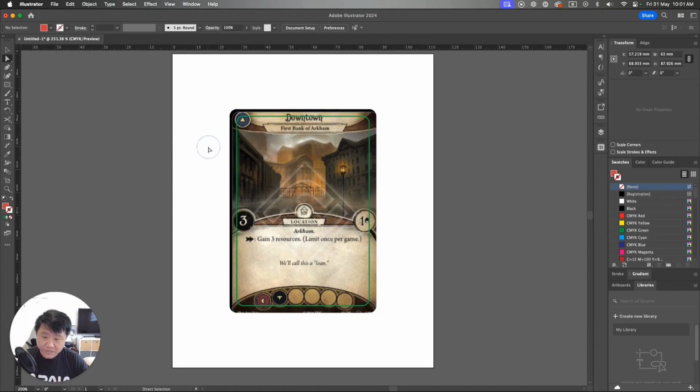So this is a 1 mil drift. Note that every manufacturer has different tolerances. Some have 2 mil drifts. If you're using a local print shop, their drift tolerance could be up to 2 mils. For mass production, it could be 1.5 down to 1 mil. Rarely would you see anything less than 1 mil. If it is, I'll explain how they achieve that in a bit. But notice that even within a 1 mil drift, I've just gone 1 mil to the left and 1 mil up, and in this case, it's quite substantial, right?